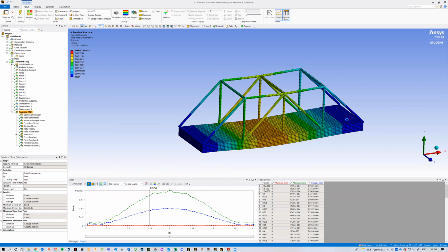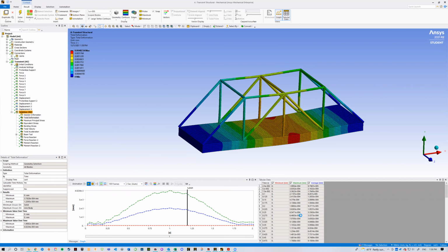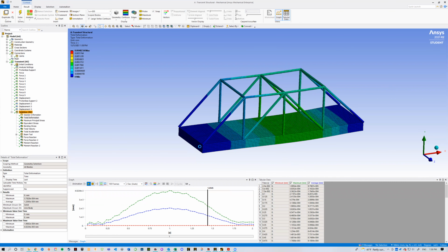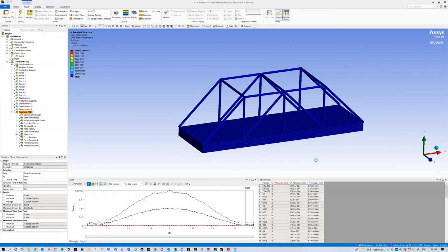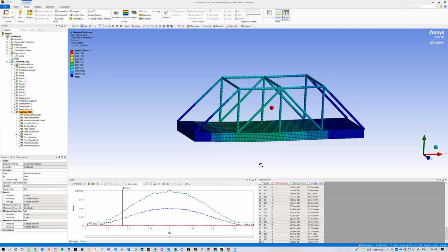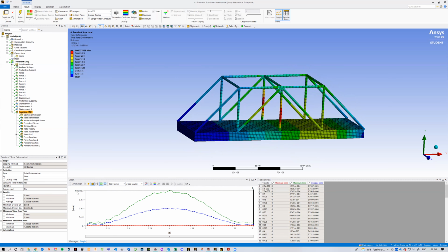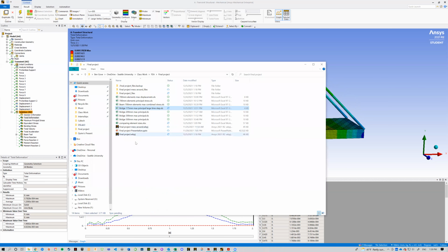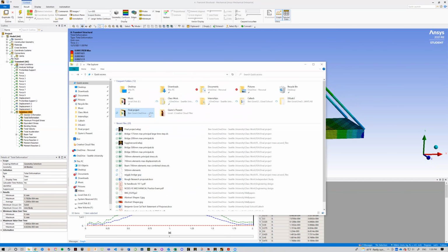So this bridge wouldn't actually deform this much. The maximum deformations are in 10⁻⁴ millimeters. And that's really just because of the bottom, I think, being solid steel. So yeah, it's rendering right now. We see a peak of 4.0234 times 10 to the negative third. And I want to show you how it oscillates way more in other situations.